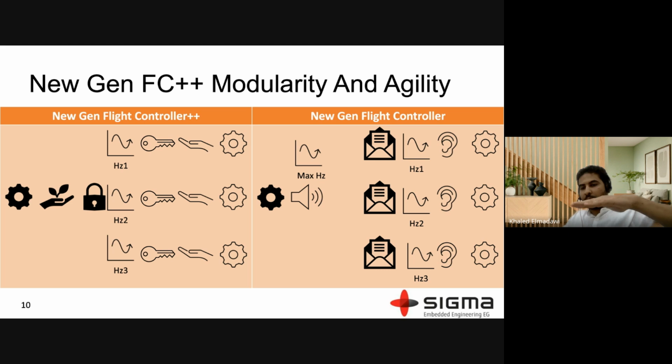So simply, the control loops work at 1,000 hertz, and the point cloud matching actually works at 10 hertz, or you will be lucky if it works at 2 hertz, something from 2 to 10 hertz as onboard processing. So you are forcing the point cloud matcher process to subscribe to a much higher frequency that it doesn't need.